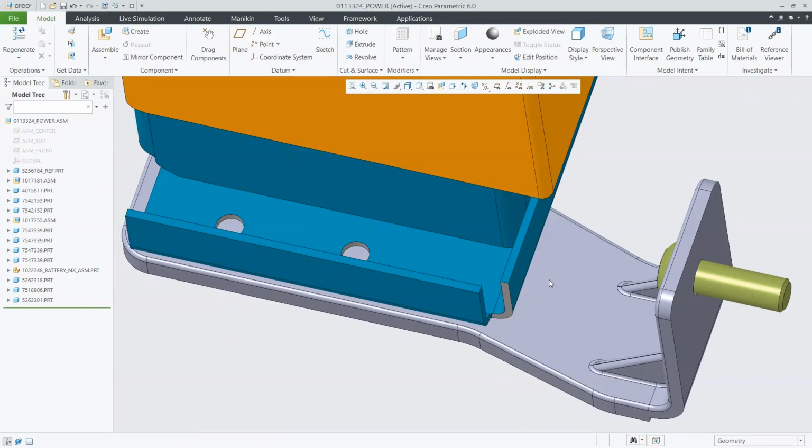So as long as it's the same original file that maybe they've made a modification to and sent you the modified model, but it's the same part number, then it is still going to reference that. You can break the link if they're saving tons of different copies and sending you tons of different copies each time. But as long as they're using the same model, or they could send you a model and you make the change on the model you're referencing, then everything would update accordingly.